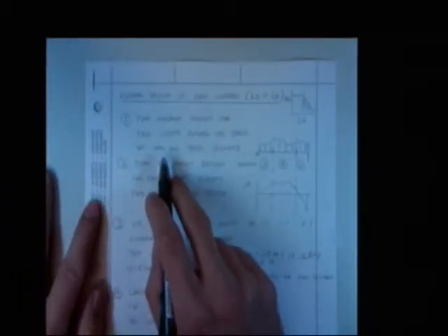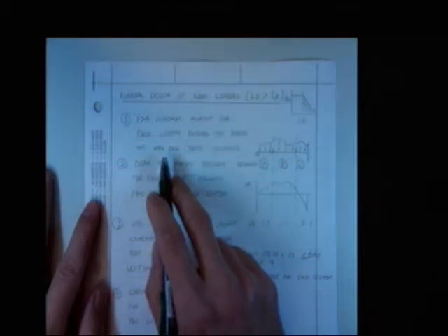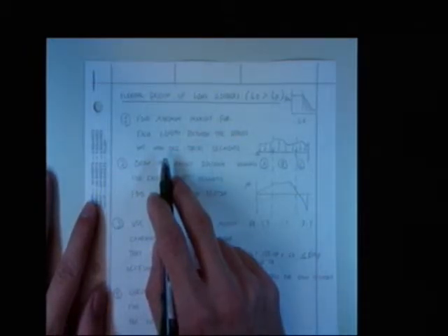Does that answer your question, Jacob? Put another column in. When you were saying stiffness, I thought you were saying stiffness, not like increasing the I. So does it make more sense now? That when we have vibration problems, it's a global problem, and you've got to increase I, or some other trick, decrease span length, something like that.